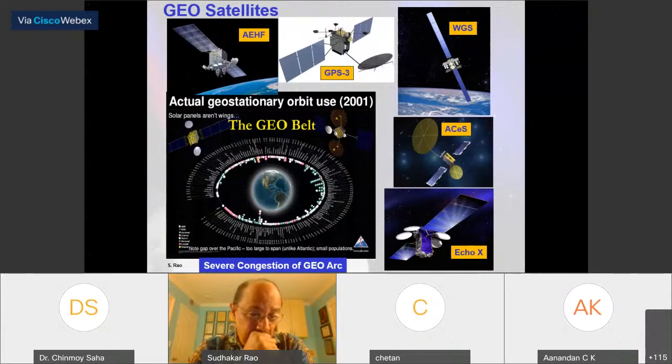The only thing is nobody knows the attenuation in V and W bands, so we are flying one experimental satellite. I think it's going to be launched soon, next month. The idea is to launch it with 5 ground stations around CONUS, the continental United States, in wet areas, rain areas, dry areas, etc., so that we can measure the attenuation constant and also the depolarization effects. Once these things are done, I think it will go into commercial practice soon.